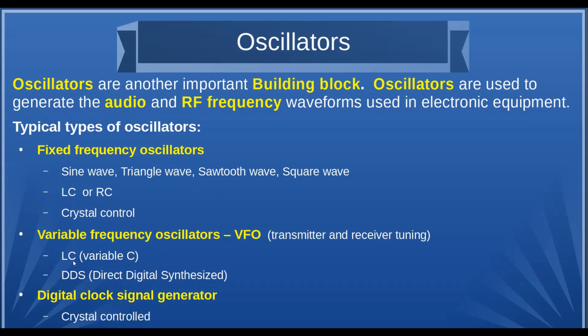And there we have either an LC circuit with usually a variable capacitor. It's harder to vary the inductor, so it's a lot easier to get a variable capacitor. And you can use things like varactor diodes, which are even smaller, and you don't have a physical capacitor with plates that you got to turn and a mechanical thing.